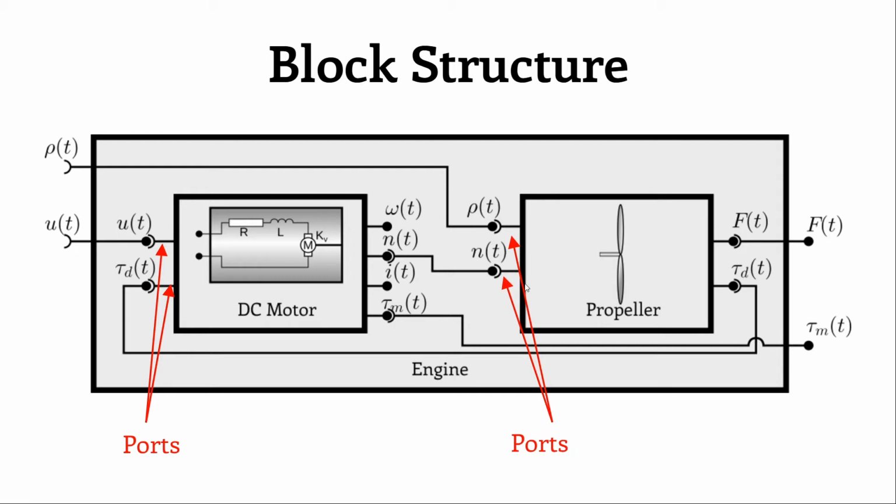They are stand-ins for the signals. And once we have created the DC motor and the propeller, we can connect up the respective source signals to these ports. We can then use the ports just as a signal, as if it was the input signal itself, and it will deliver the value that is provided by that signal.